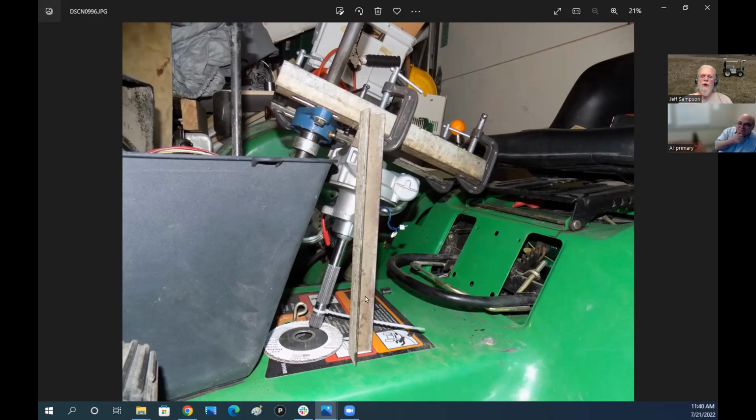That would be an option. One reason I want to weld these vertical braces to this horizontal brace down here is because I'm trying to get that to be one piece, because again, here's the steering shaft going up and down here, and here's the bearing. So this whole thing can rotate back, and it can rotate around that. And I need some way to prevent that from rotating. Now right here, I don't have a lot of leverage between the steering shaft and where I'm holding on to it. So I don't know that's going to be strong enough to hold that. It could be if it tries to turn, it's just going to bend these sideways. And that's why I want to weld it at the bottom. I can weld it in several places and get that fairly strong.